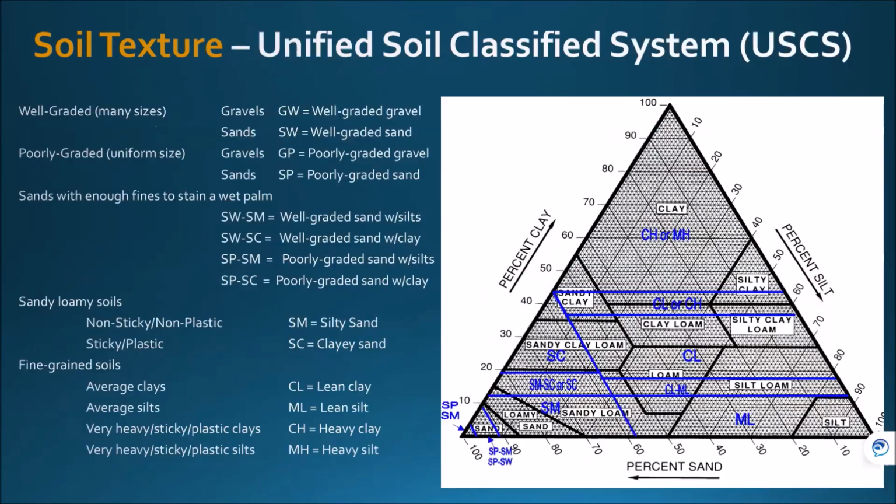Next slide, please. So then, as I mentioned before, there are two different ones that we utilize in a lot of our construction activities. We utilize the USDA, and then the engineering folks utilize the Unified Classification System. It's a more simplified, larger grouping of soil materials, and they're looking at it from the perspective of how well these soils can be manipulated.